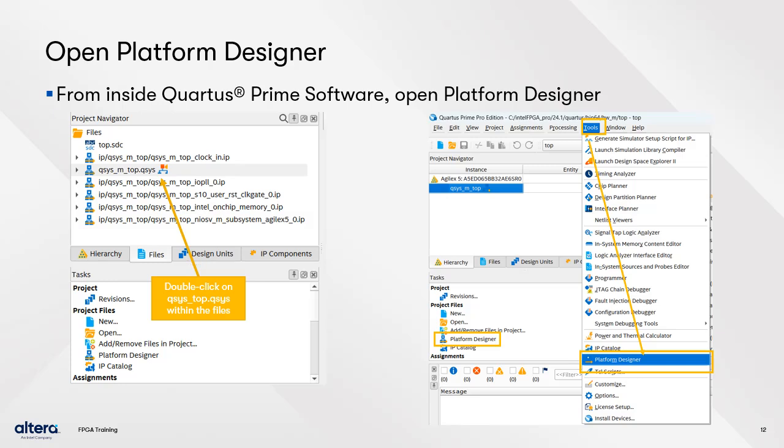The Platform Designer System Integration tool saves significant time and effort in the FPGA design process by automatically generating interconnect logic to connect intellectual property, IP, functions, and subsystems. It significantly simplifies the process of generating a system. The idea is to have all components, including custom ones, conform to a standard interface, such as Avalon or AXI, and since Platform Designer understands these interfaces, it can automatically generate the interconnect for those components and interfaces.